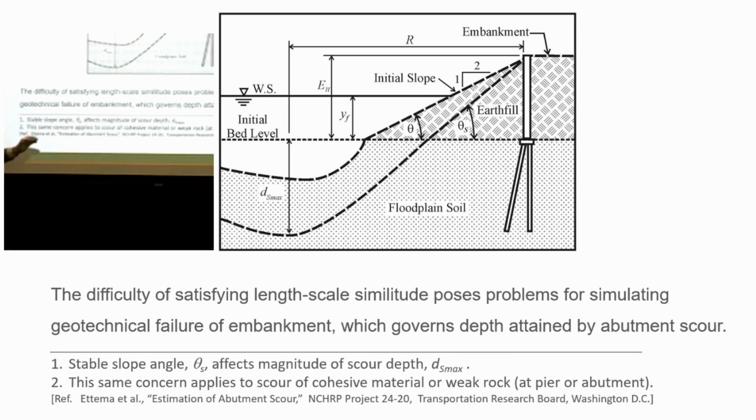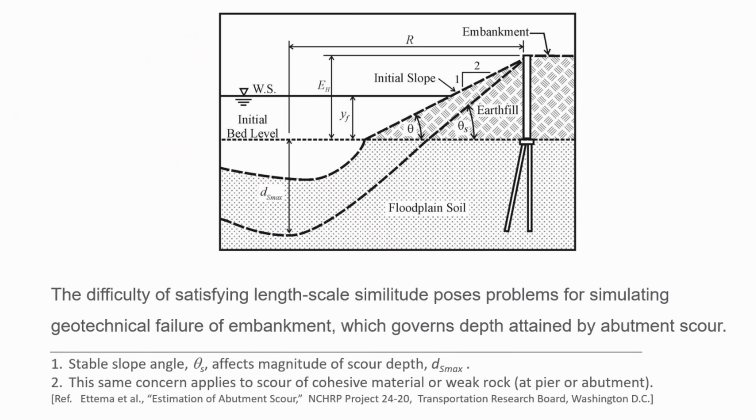Plus, if you have a rock vane, for instance, a rock pile tumbling into the scour hole, the rock will remain in the scour hole and armor it, so you won't get much deepening. And that's part of what the study with Drew and David and Nathan was about, to design these to allow this to occur, to have a sacrificial length.